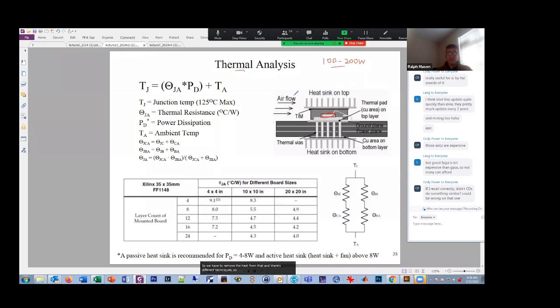So often, this is showing the example of a chip. Here's our die. It's in a package. And we've put the package with a thermal connection, some thermal paste here, and we put a heat sink on top. And so this heat sink is basically a piece of metal with a lot of fins that will radiate heat out from it. Now, the chip that we have in the lab, I don't think you've done that, but if you ever look in a laptop or a desktop, every processor will have a heat sink on top of it. And so you'll have conduction, and even to improve it further, they'll have a fan, and the fan will blow the air to remove that radiated heat even faster.